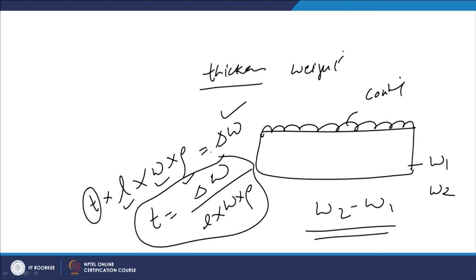So, now here I will summarize this presentation. In this presentation basically I have talked about two aspects. One was the surface roughness, and there are two methods for measuring the surface roughness: one is the contact type and another is the non-contact type. Contact type is one of the most commonly used methods for measuring the surface roughness, as it gives the direct reading of the surface roughness value, while non-contact type methods are good for measuring the surface roughness of moving objects. However, this method may not be very accurate.